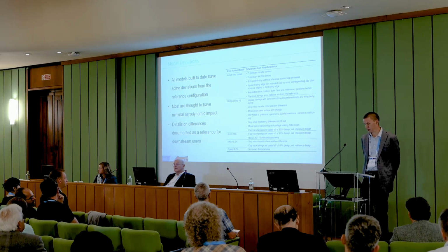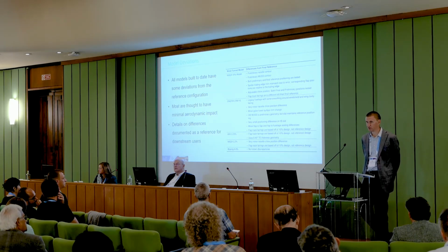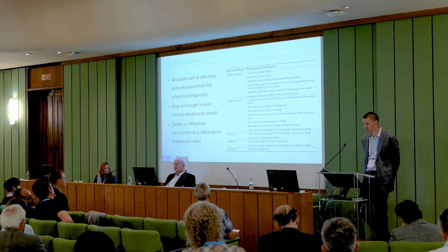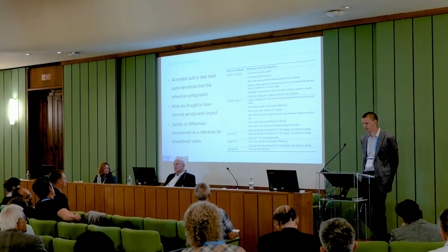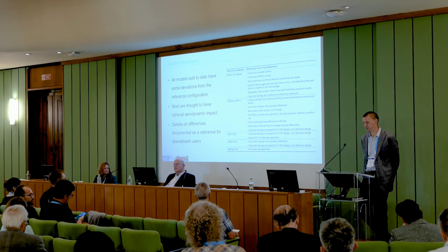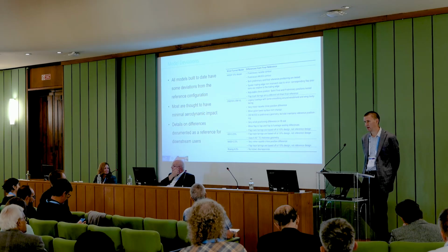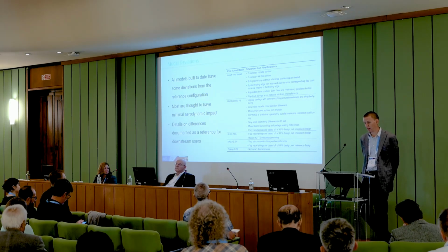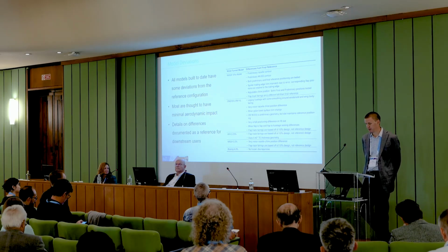That drives some very small positioning differences to the inboard slat because we try to keep the critical distances comparable. The flap to flap and flap to fuselage sealing differences are a little bit different on this model, primarily because we didn't document that in time. And then again, the flap track fairings are based on the 10%.